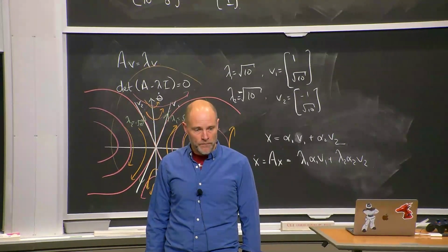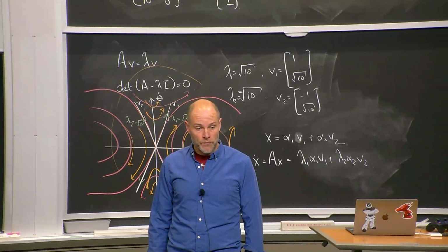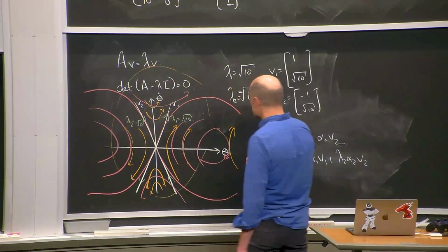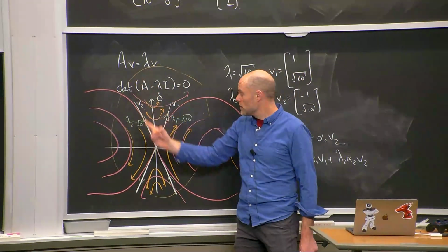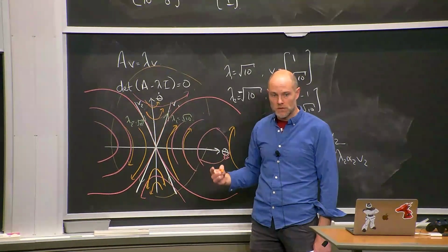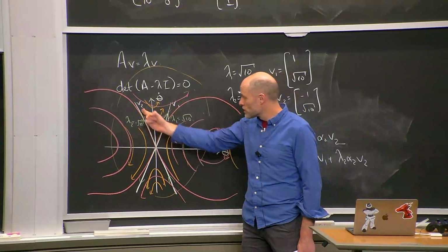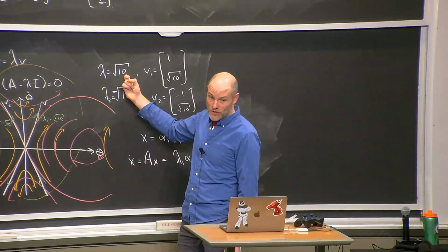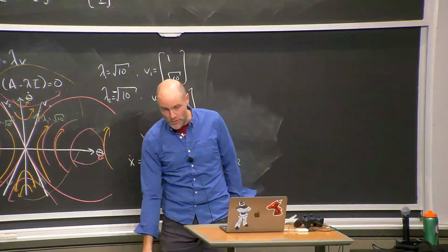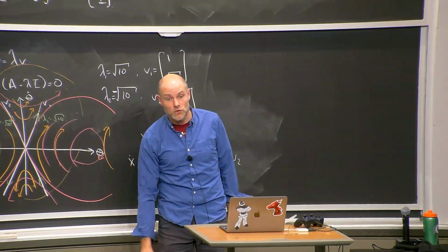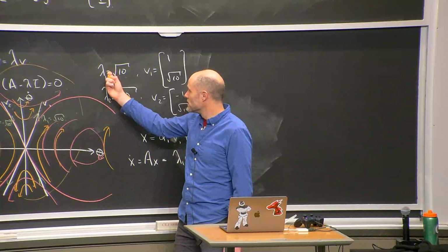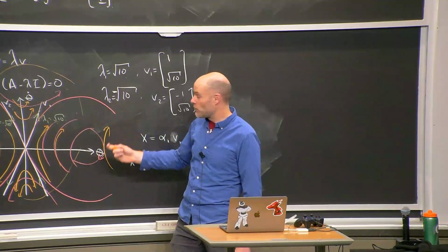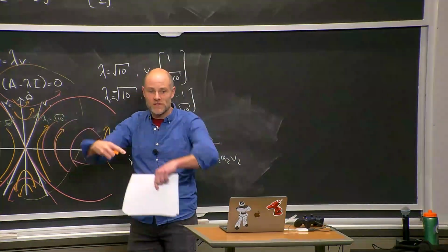Yeah. What's that? Oh, good. Okay. Basically, the eigenvalues of A have to be negative in order for the system to be stable. The original pendulum is actually unstable without a controller at the top. If you were to linearize around the bottom, you would get 2 negative eigenvalues, and it would be stable. Our goal will be to find a linear controller, LQR controller, that makes those both negative. And that will change the vector field, so everything's pointing towards the origin.